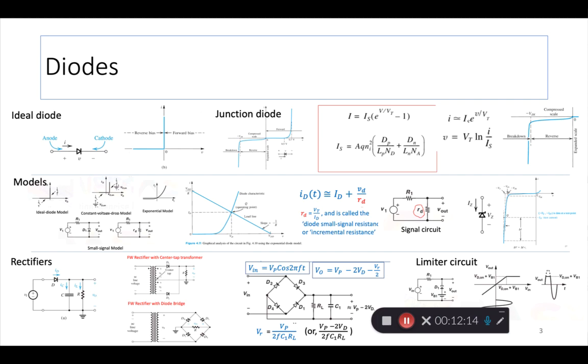And so voltage regulation means maintaining a constant voltage, or as constant as possible. There'll always be a slight change, but mostly constant, even though the current changes very significantly. The current might change 3 or 4 times, but the voltage changes hardly 1 or 2%. And that property is called regulation, and diodes in the reverse direction are used for that function.